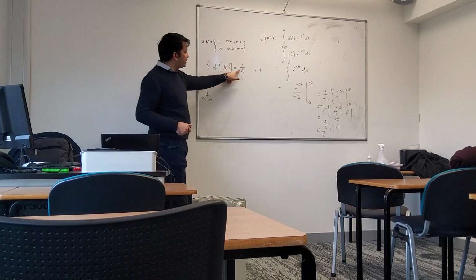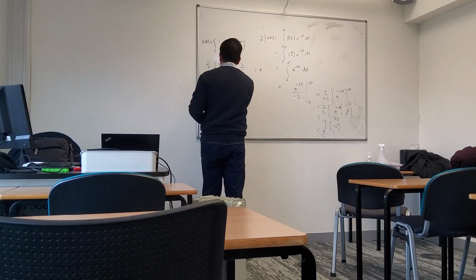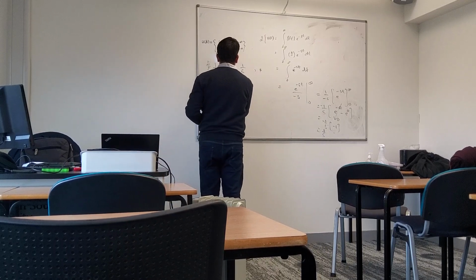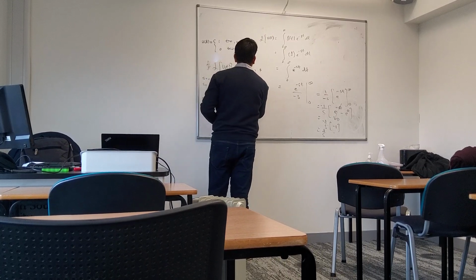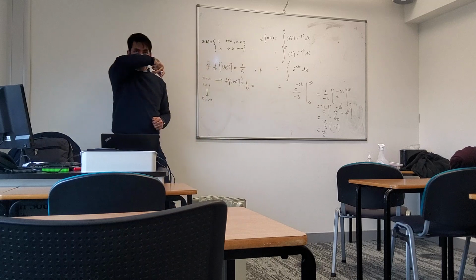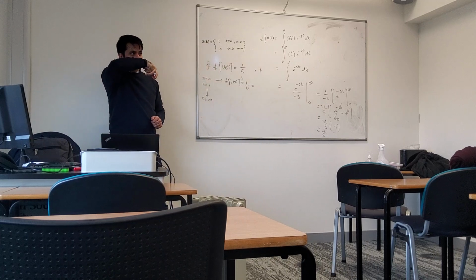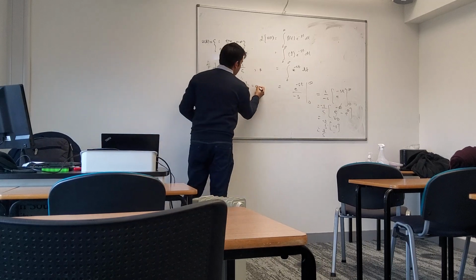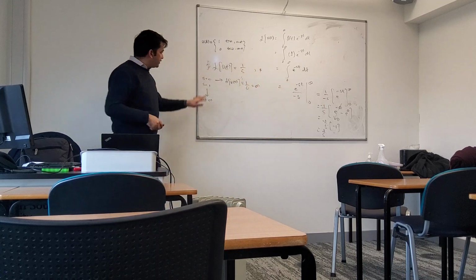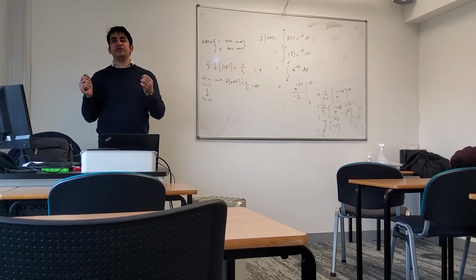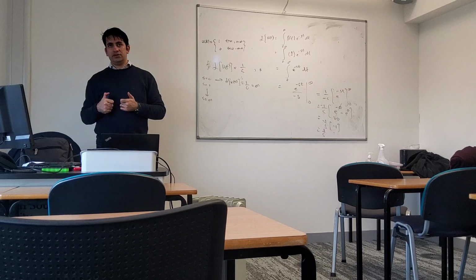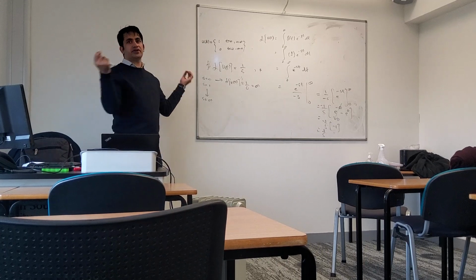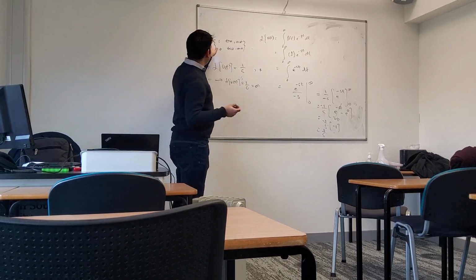So if you put s equals 0, the Laplace of u of t is 1 by 0. What would be the answer? 1 by 0 is infinity, right? It means that s equals 0 means zero frequency. Zero frequency means DC, a constant value, which is true in the time domain as well.